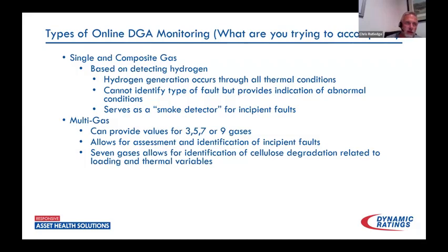Okay, so everybody does that power factor every 5 or 6 years, and I've seen many events where there was a great deal of mechanical movement of the windings that the capacitance really didn't change that much for power factor. However, blocking had greatly shifted, some bracing had been damaged, things like that, things that would have been a failure had they been re-energized. So these are things to consider, other failure modes that would fall outside of those which would be indicated through multi-gas detection. Acetylene is not always the first indicator of failure. Well, I guess that would be the best way to put that.